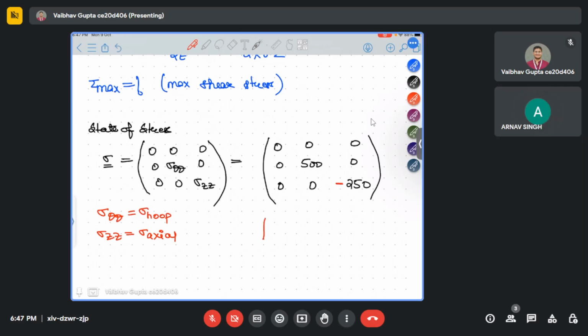Suppose this is a fixed beam, a simple example. Suppose I'm heating it. This beam tries to expand its length, but due to the fixed end, can it stretch? No, sir. So the fixed end will try to compress. It will exert a force onto the beam so that it can't move.